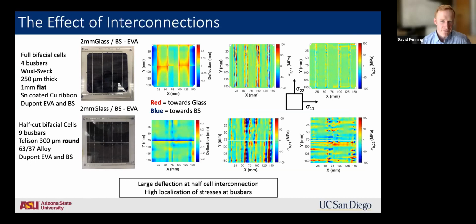So eventually, in a damp heat test, the encapsulant appears to reach equilibrium. Of course, it depends upon the size of the mini module and when that equilibrium is reached in the center. But even for example, these 8x8 inch mini modules, it's a substantial portion of a damp heat 1000 test in order to reach equilibrium. And so those equilibration times can be quite long.